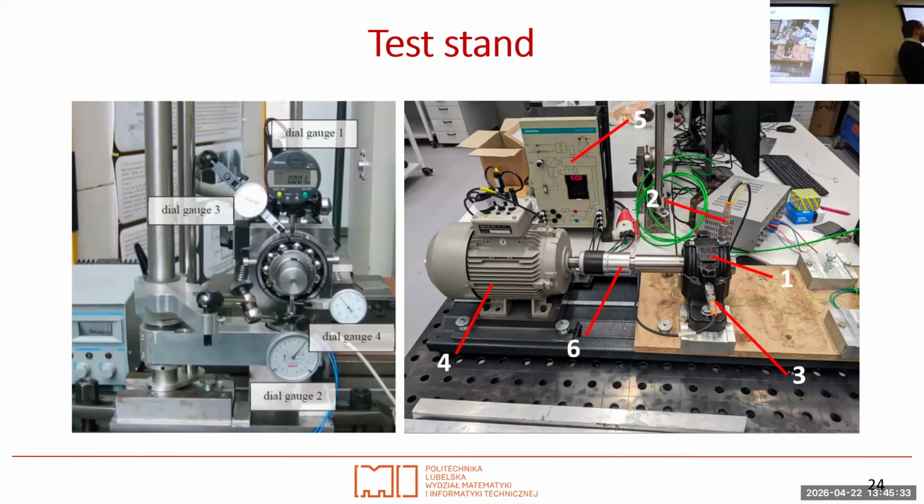Okay, and after the measurement and the setting of the clearance inside, we put it in, because this is actually this part. So this bearing is closed inside it. In this housing, this part you can see is behind this part of the shaft, just connected with the coupling. Yeah, so this is how it was mounted. It was shifted like this, and we have used two accelerometers to measure the clearance.